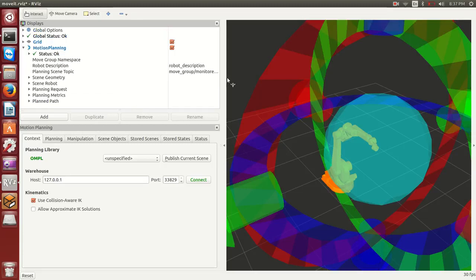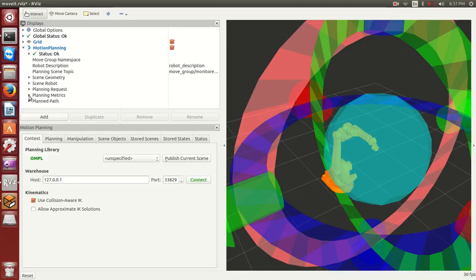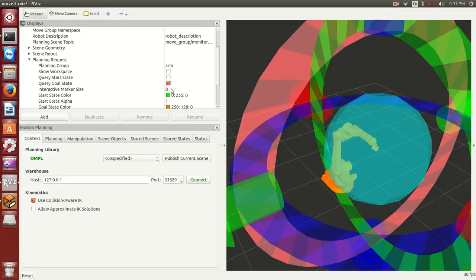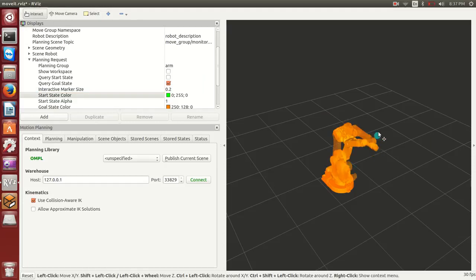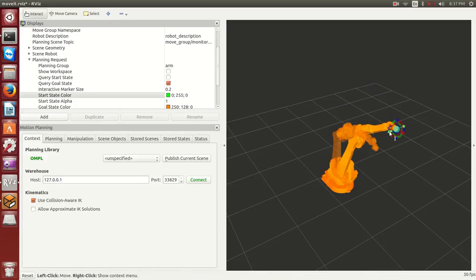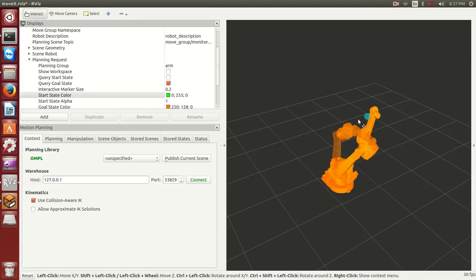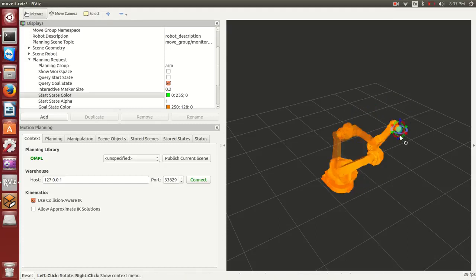So there's this bug. Here I go, calling everything bugs, but this one seems like a bug. That is coming in large, the little controller there, so I'm going to tune that down. This is on 0, but if I put it on 0.2, I'll take care of it. So this is kind of what typically happens when you use Moveit. You get this arm, you can pull it around. So this is just forward kinematics going anywhere, and then inverse kinematics to travel in a particular Cartesian direction or any generalized coordinate.